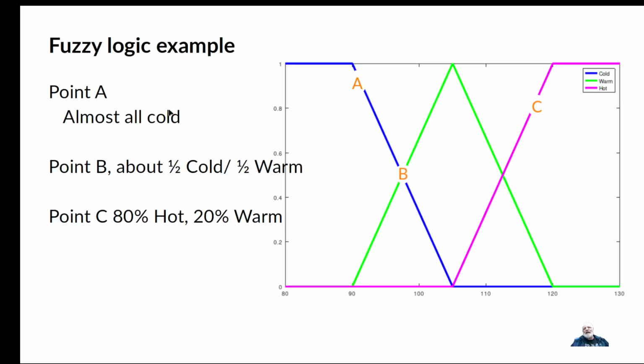But here at point B, we're still cold, because we're looking at this pattern where 105 is where we want the heat box to be. We're not quite there, so we probably don't want the fan on at all, but we want the heater on. But we maybe don't want the heater on full blast now. We're getting warmer, and we don't want to overheat it. So we maybe turn it on with a duty cycle of, instead of 255, maybe 230 or 200 or 180.